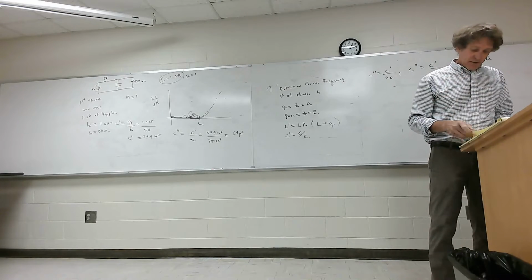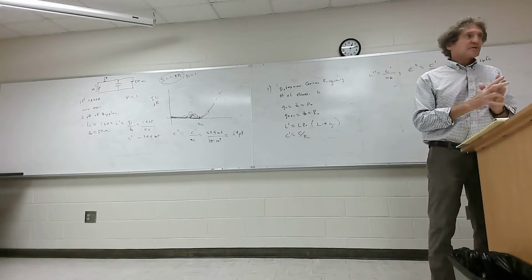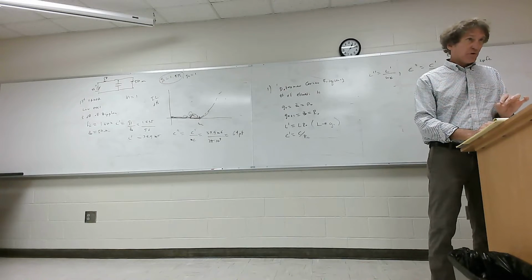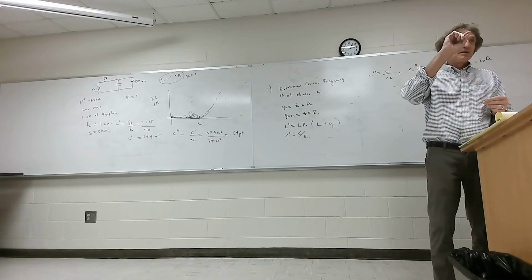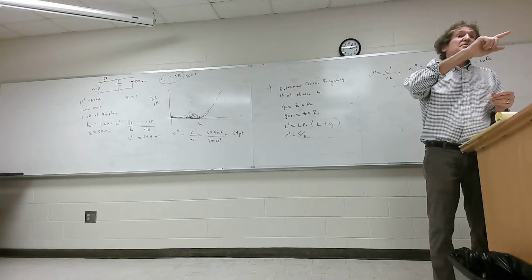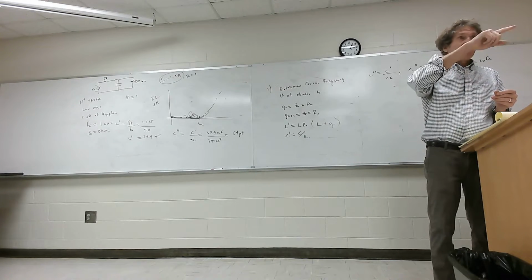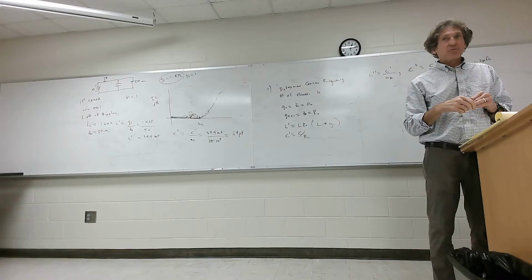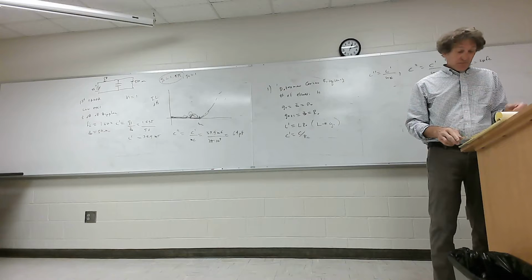Next thing I'm going to do is another example. And I want to say one thing. The key is getting the values G1, G2, G3 from that table, and then realizing you have one of two designs for low pass. Either you have series inductance, parallel capacitance, series inductance, and this would be a low pass filter, or you're going to have parallel capacitance, series inductance, parallel capacitance. Either one will do the same job. The performance is identical. The values will change though, depending on the type. And the one we did was the simplest filter of all.